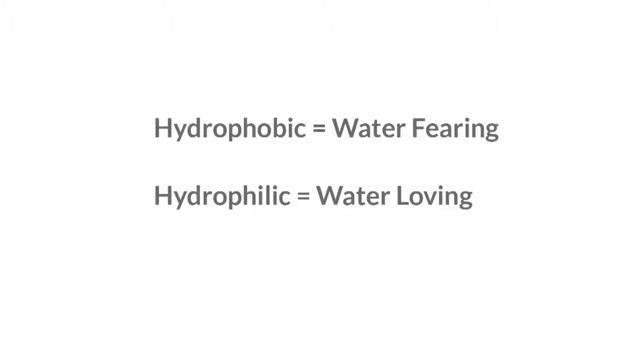Instead, we need to use more efficient processes, and the one that's commonly adopted is a process called flotation. Flotation utilises the fact that the metalliferous ore particles and the gangue minerals have different interactions with water. Fundamentally, flotation relies on the fact that hydrophobic ore particles and hydrophilic gangue particles can be separated. Hydrophobic means water-fearing, and hydrophobic substances fundamentally repel water. Hydrophilic means water-loving, and these are attracted to water.